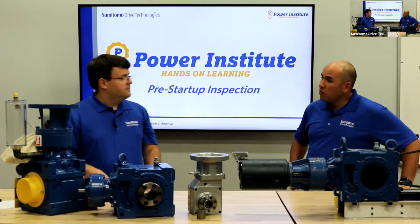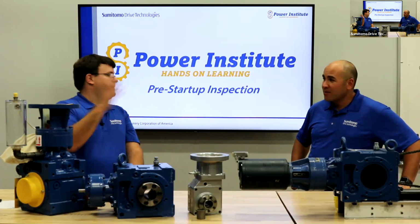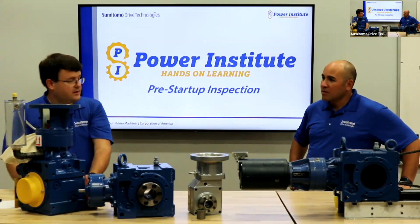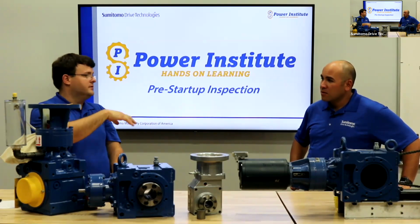Now, what if it's not oil? If it's grease, you can mount it any which way. The grease units do not have this external oil. They're completely greased, so those you can mount in any direction. It doesn't have to be 90 degrees. It can be anywhere in between.